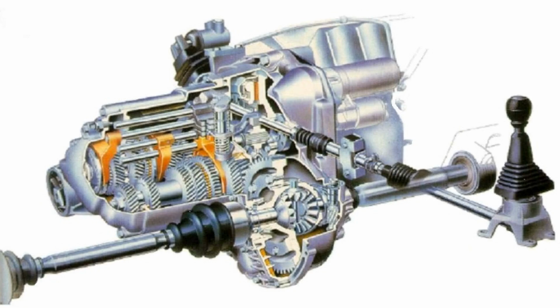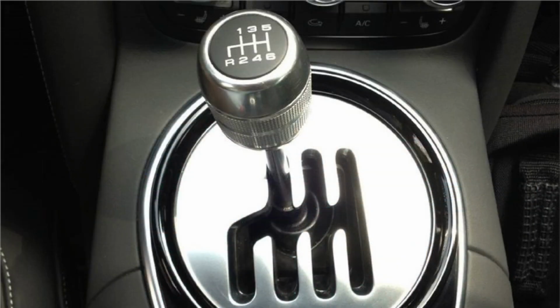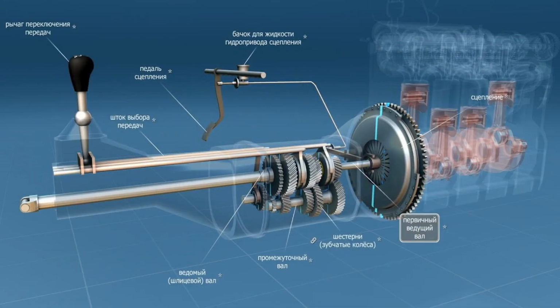The transmission fluid enters the torque converter, which then activates the clutches and bands. These in turn determine which gear ratio to engage, and the planetary gear can then be configured for the right gear combination. All parts of the planetary gear can be locked or unlocked to determine the gear ratio. The video below will help you understand the different gear ratios that can be achieved.